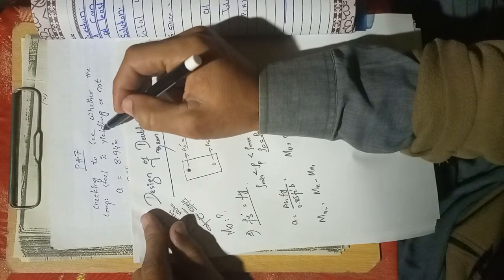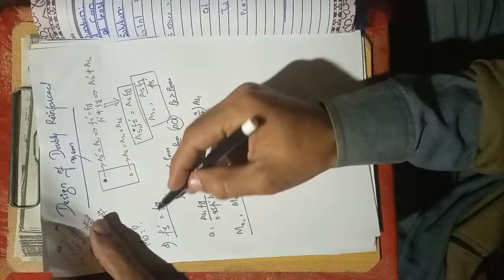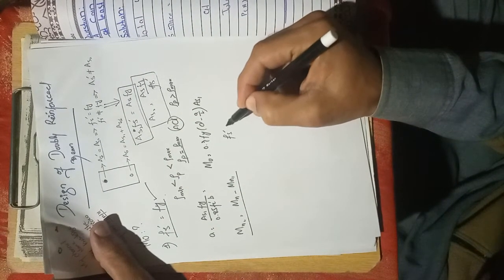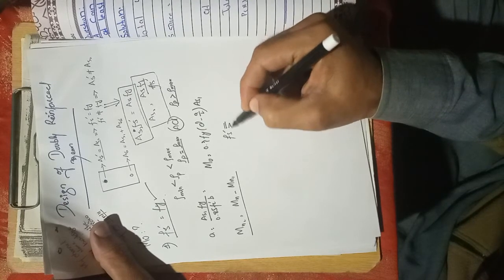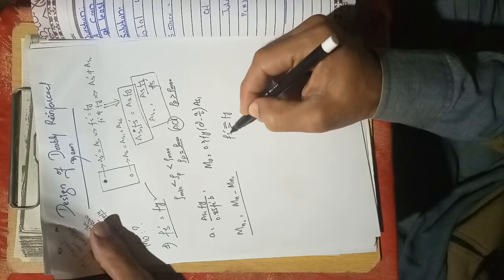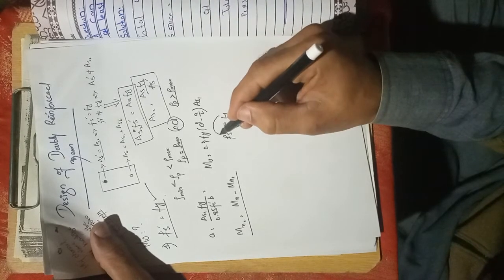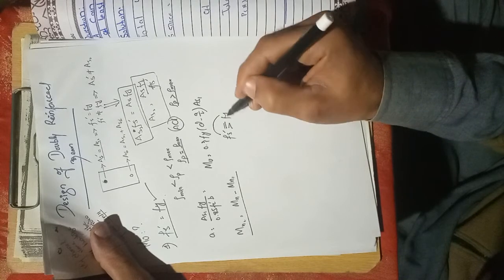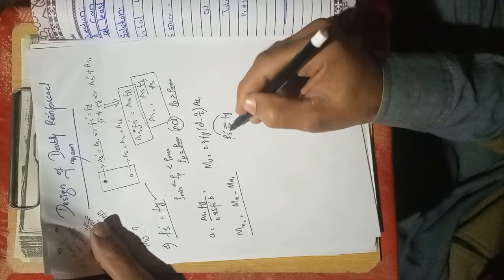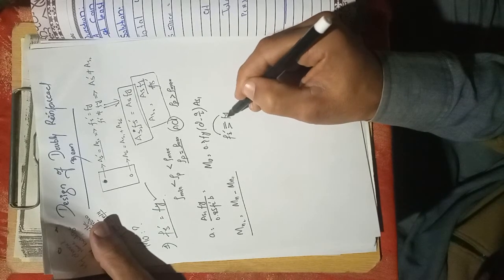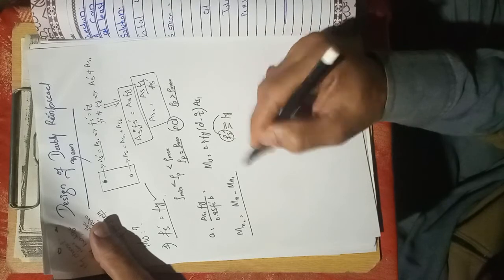Here we have to calculate the Fs prime value because we have to check this assumption, whether our Fs prime value is equal to or greater than the Fy value. This is the compulsory criterion that you have to check: whether it is greater than Fy, equal to Fy, or less than Fy. If this value is greater than Fy, this means that our compression steel is yielding.